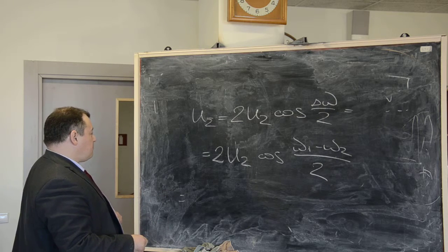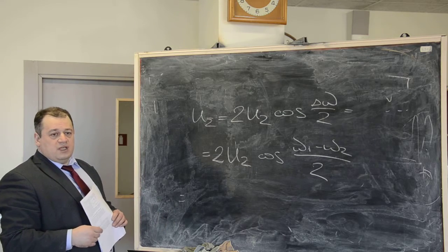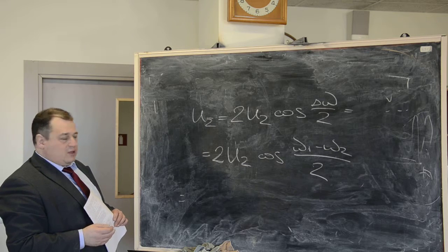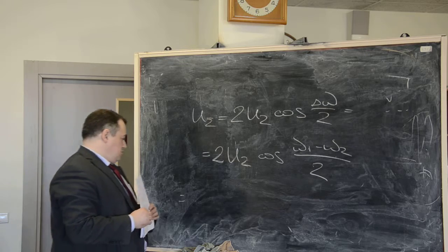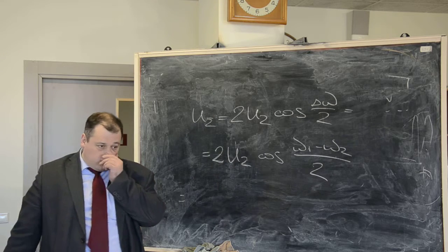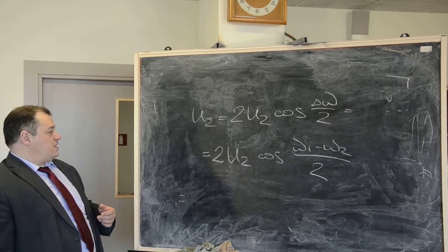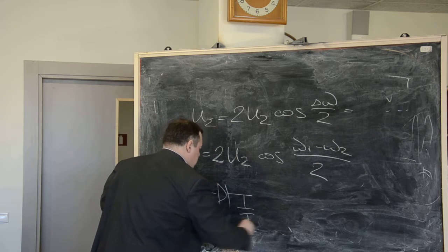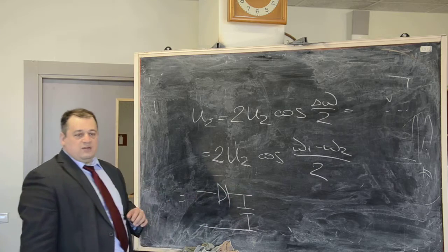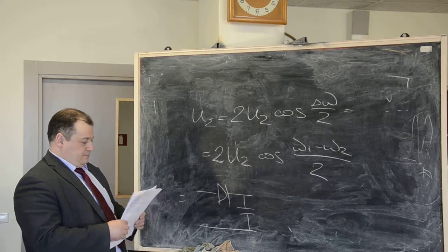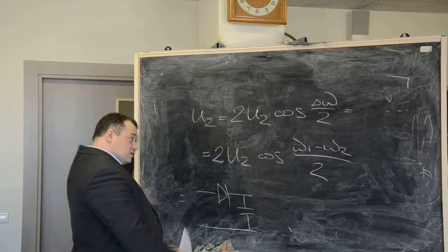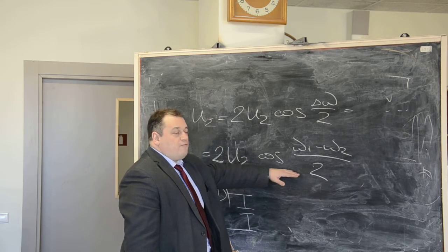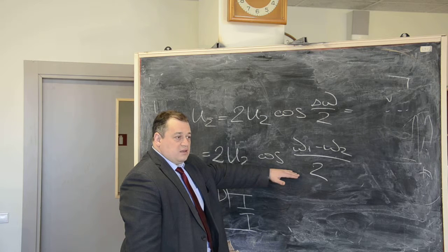If we apply such voltage to any nonlinearity, it may be nonlinear resistance or a diode, or take an absolute value, anyway the resulting output will contain, in the easiest case, a DC component and two signals. The strongest one will be the frequency difference cosine.